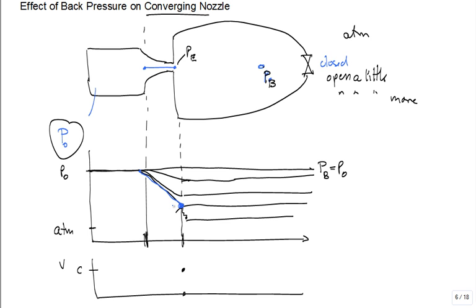Well, it's an abrupt change in the flow condition across it, such that it's highly irreversible, and you have in this case a pressure drop across that shock, because the pressure coming out jumps to a low pressure, and there it goes. It's an abrupt change in pressure. And so you can continue to decrease that back pressure by opening the valve a little more, till it gets down to atmospheric pressure. But what you did is you increase the strength of that shock. All right.